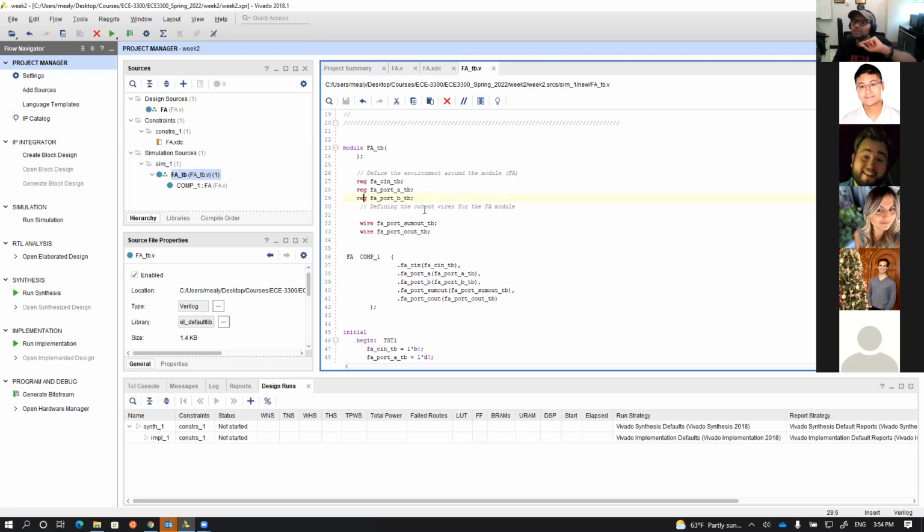A reg is a wire that goes with a clock, meaning it goes into a flip-flop, for instance, so at the end of the day it stores something. But a wire is just a wire. It's a connection from point to point, and there is no delay inside. So reg is kind of like something that stores a variable, involved in a process to store? Yes.